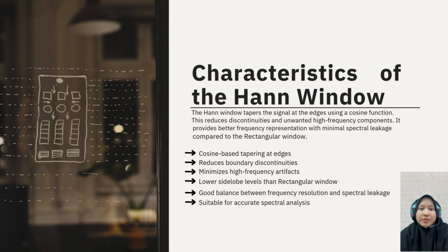Firstly, cosine-based tapering edges. Second, reduced boundary discontinuities. Next, minimized high frequency artifacts. Next, lower side lobe level than the rectangular window. Next, good balance between frequency resolution and spectral leakage. Lastly, suitable for accurate spectral analysis. That's all for me. Thank you.